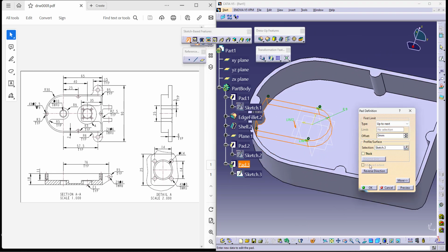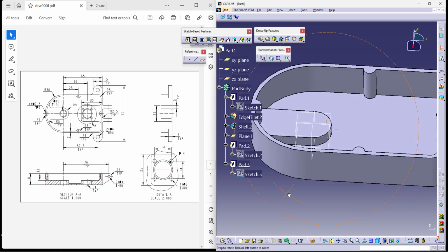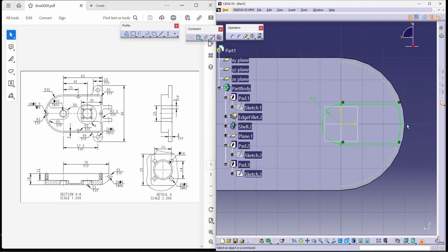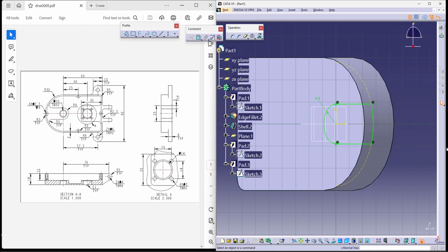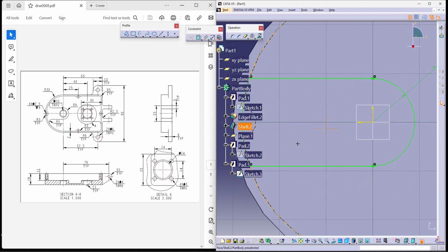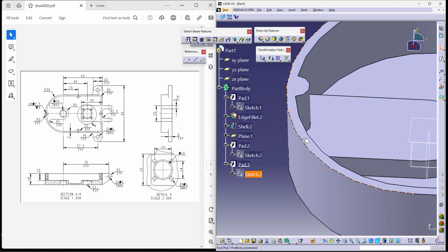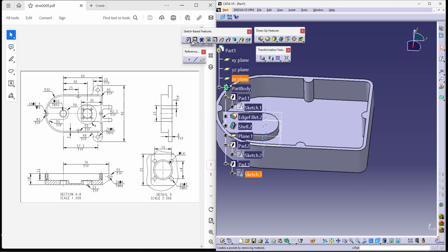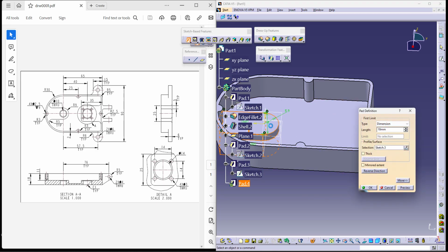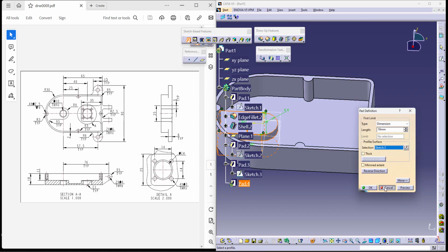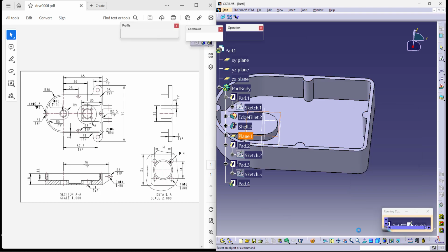Now this should be added up to the immediate next surface. You cannot give a dimension for it, so it's automatically added up to the end of your surface. If you are thinking this is causing an issue, you can also take the reference of the semicircle this way and then add the material too. That is also advisable. Similarly, again following the plane, for taking a new pad, I'm selecting the plane as my sketch.